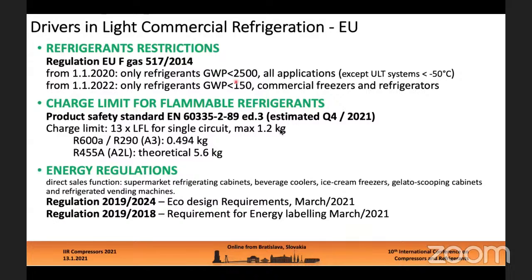Linked to the F-gas regulation, the second driver is the charge limit for flammable refrigerants. Most of the equipment in the light commercial segment is approved according to product standard 60335-2-89, which recently, in 2019, the IEC version was updated in terms of the charge limit for flammable refrigerants. So the new edition 3 of this IEC standard allows a charge of flammable refrigerants up to 13 times LFL for a single circuit, but not more than 1.2 kg.